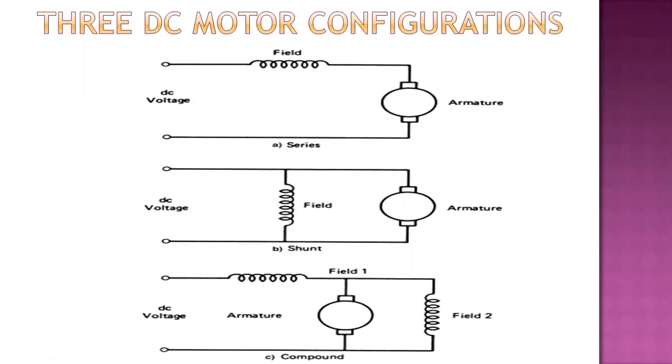So control of speed and torque of these large machines requires very high power DC electricity. Such power is derived from the power electronics devices described earlier. And in general, the three-phase AC power is rectified using switching technology to produce the required high voltage and high current DC electricity also.